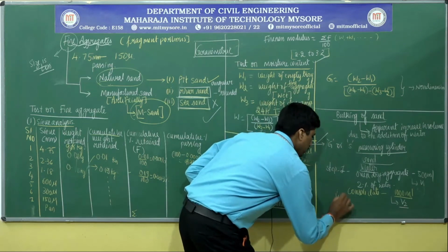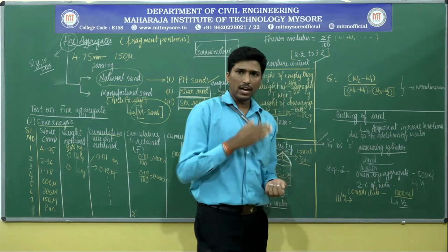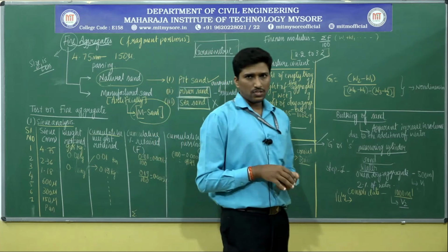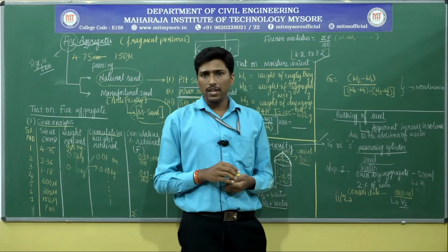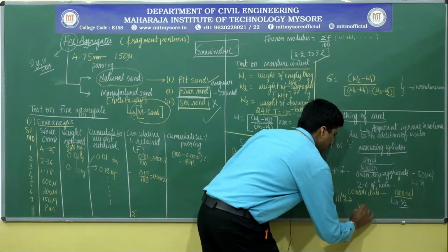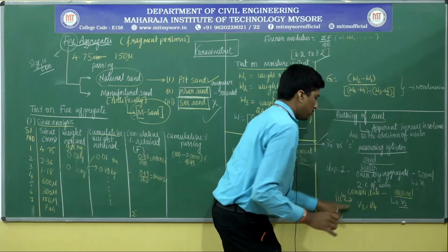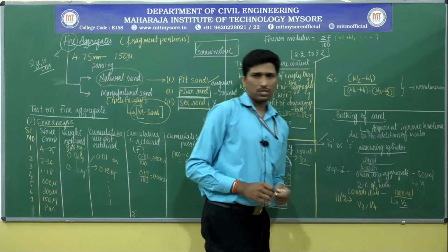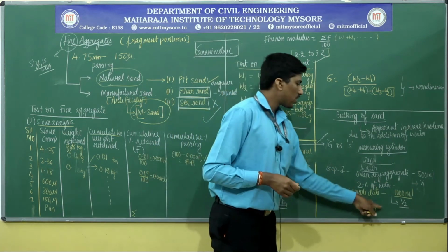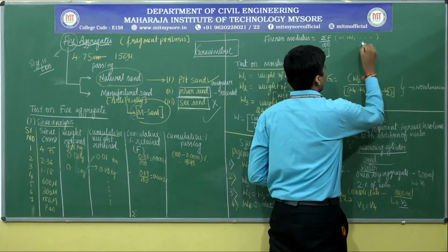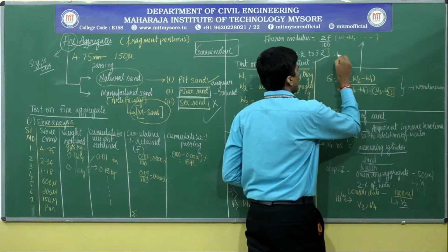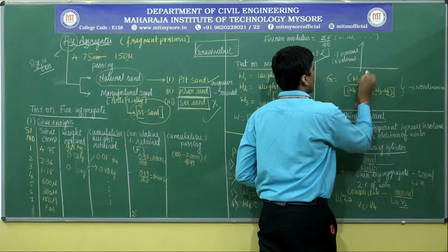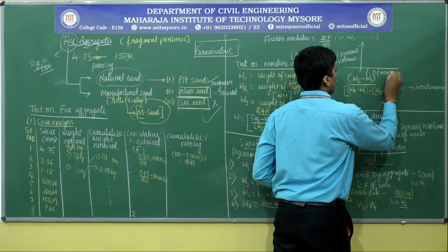Similarly, you conduct the procedure on a continuous basis so that the curve can be obtained, or the stage is reached where you add more and take the volume as V3, then V4, adding 2% extra each time and getting the volume. Later, you need to make a list of the percentage increase in volume against the percentage of moisture added.